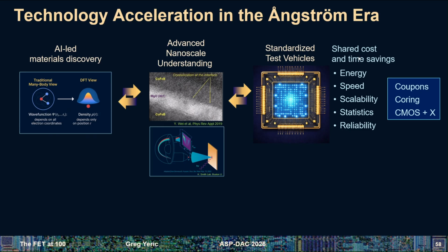By advanced, I'm talking about the things we care about from the product side: can you make 1 billion of these things at 10 nanometer size? Do the properties scale from the micron lab dimension to the nanometer scale? When they scale, do you really get the energy and speed that you thought you were going to get? Because again, these are all going to have the same problems like the MOSFET, where you've got a great property, but as you scale it to the nanometer regime, all the parasitics are not going to help you out.